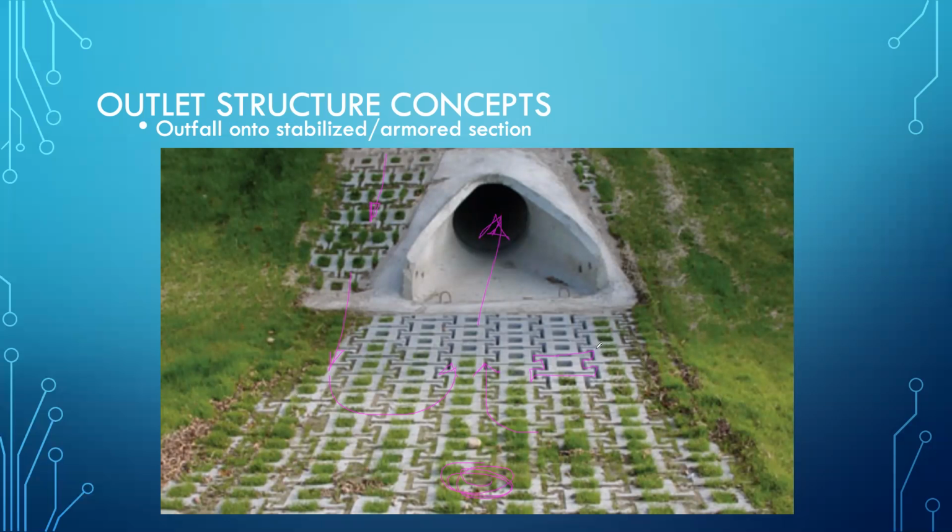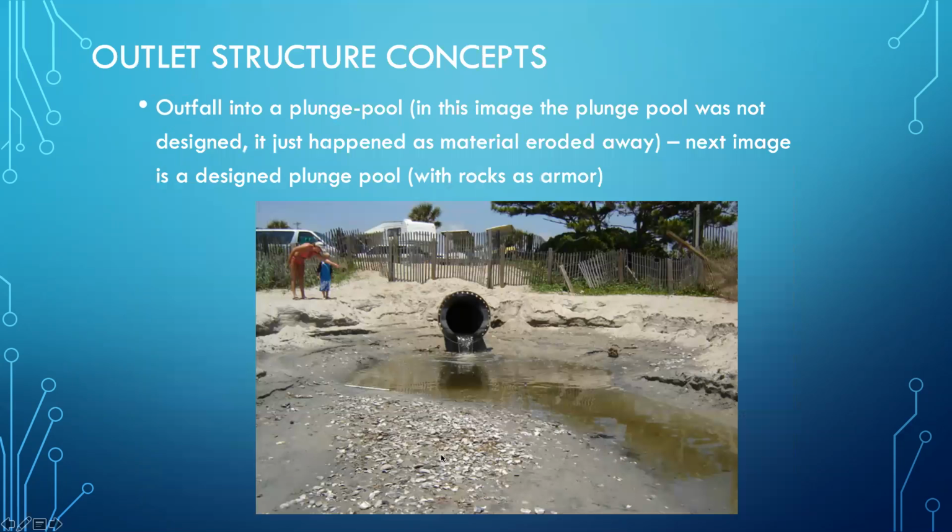The placement of these is not cheap, but it's fairly attractive because they're put in place, backfilled with soil, and vegetation can grow up in the open cells between the interconnections, and that tends to make them fairly rugged and capable of handling the high-speed shear forces that occur during the high flows. So that's one type of armoring, and it goes by a lot of different names: interconnected porous pavers, revetment, interconnected revetment, a lot of different words.